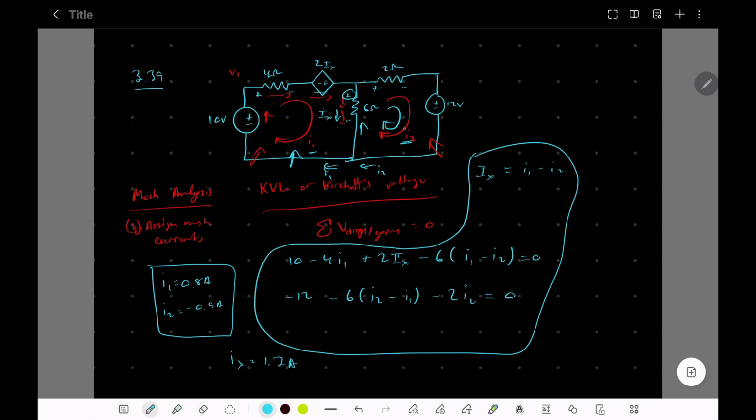And that makes sense because I2 is actually going in the opposite direction, and so when these two feed in this way at this junction here, the only thing that could happen is for them to add, so 0.8 plus 0.9, you get 1.7, and that's the current flowing through the top vertical branch in the middle. And that's that for that question.